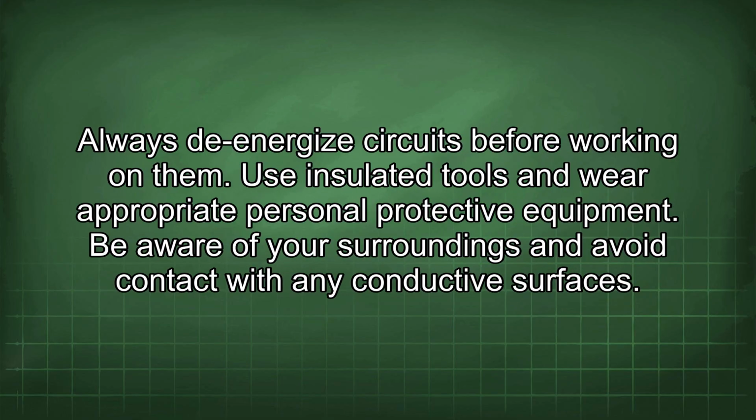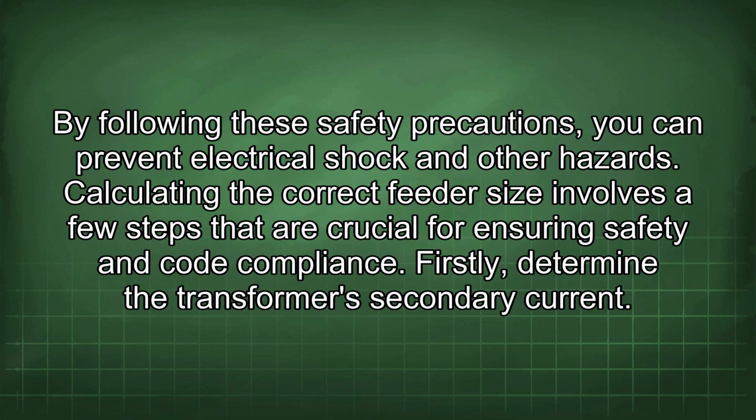Always de-energize circuits before working on them. Use insulated tools and wear appropriate personal protective equipment. Be aware of your surroundings and avoid contact with any conductive surfaces. By following these safety precautions, you can prevent electrical shock and other hazards.